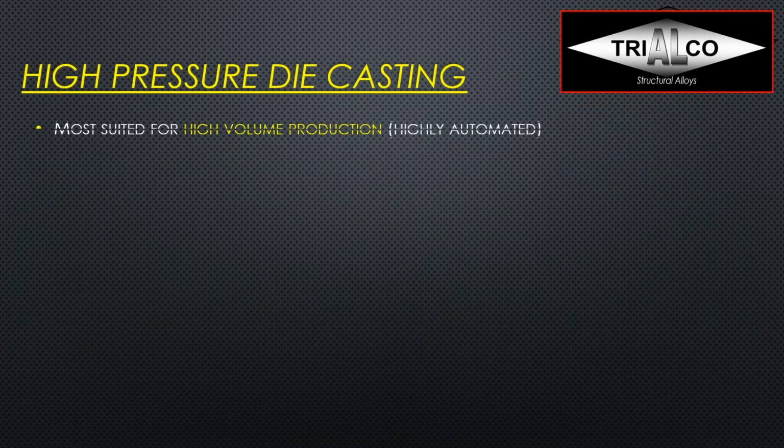Now let's start with the most common casting process in North America, and probably the world: high pressure die casting. It's really most suited for high volume production. It's ideal for that because it's highly automated with an extremely low cycle time, sometimes in the range of 30, 40, or 50 seconds. Even for big engine blocks, you would talk about 90 seconds. And you can also have several cavities in one die, so you can make a lot of parts very quickly.